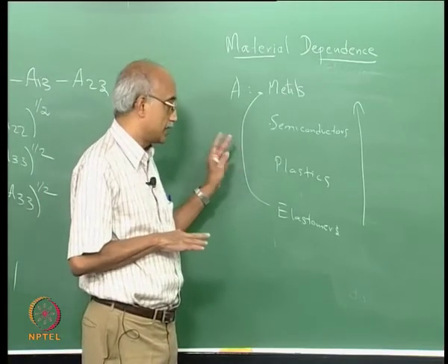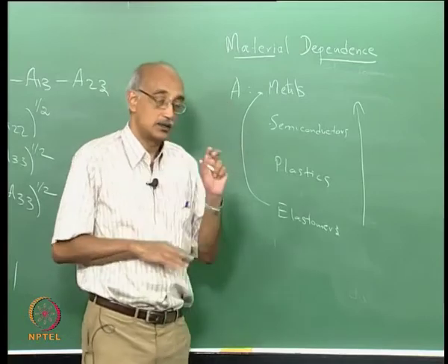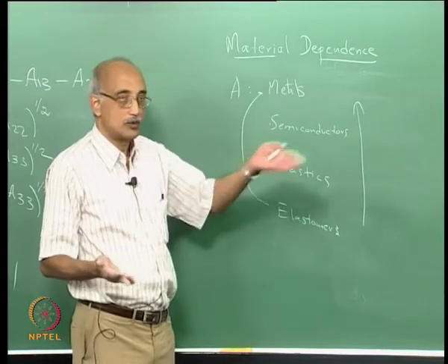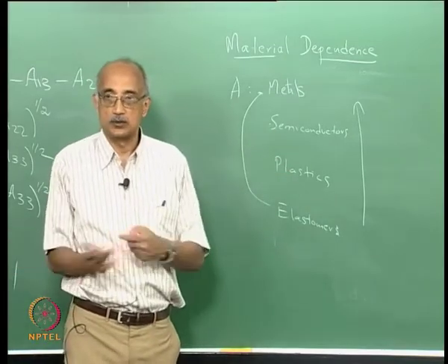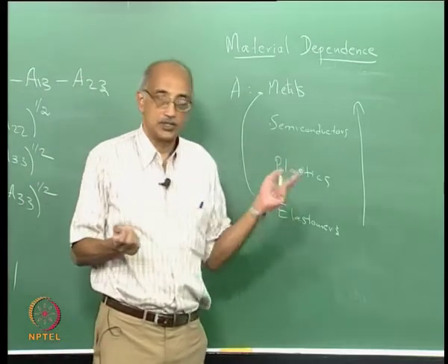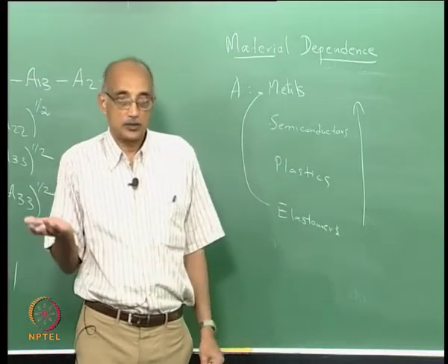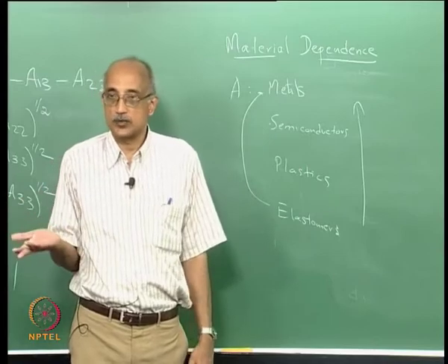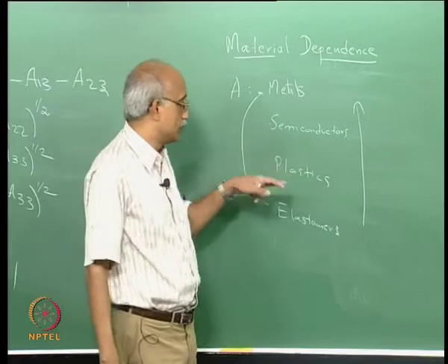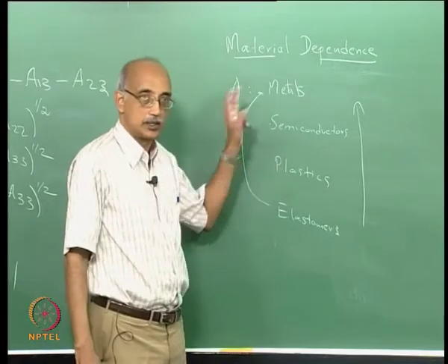And again, remember that we are only talking about one type of adhesion force. The net adhesion force is a combination of all the ones that we talked about. So, you may choose a material which minimizes one type of adhesion force, but at the same time it might actually increase another type of adhesion force. For example, if you are trying to reduce Hamaker constants, you might want to use plastics instead of metals, right?